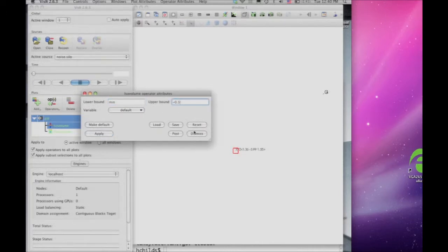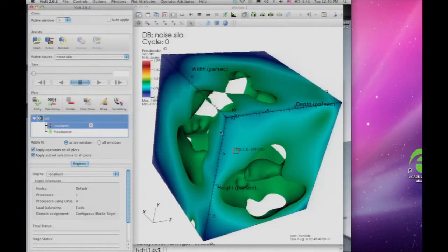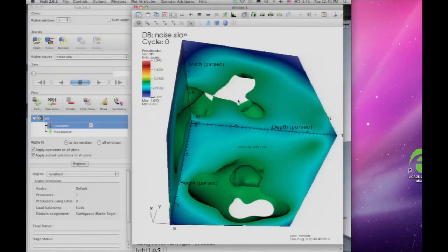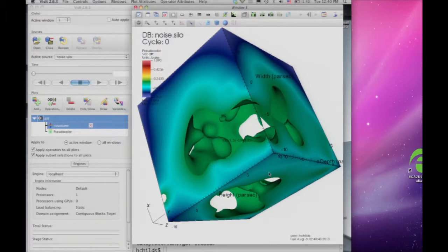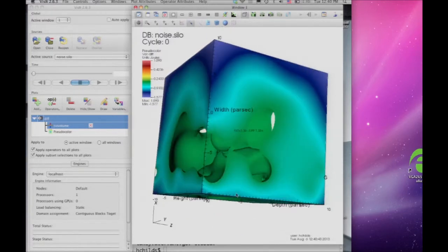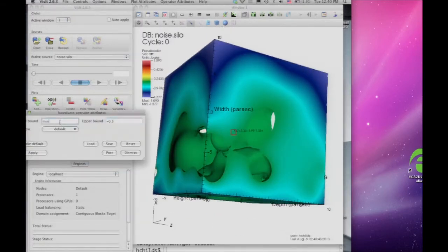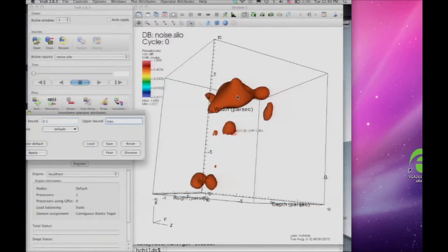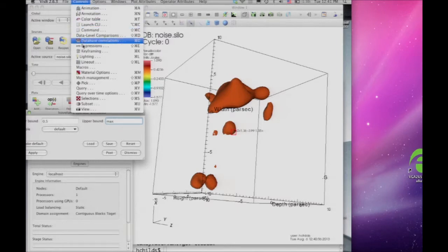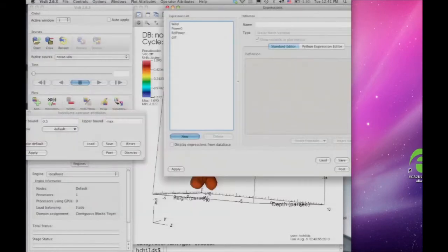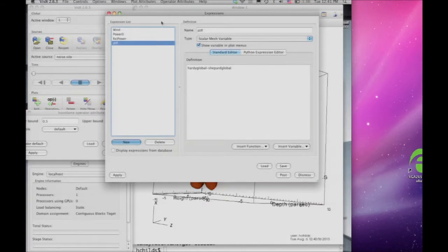Mesh quality, so if you have an unstructured mesh, ways to calculate shape, shear, skew, stretch, taper, warpage. There are various definitions to measure mesh quality, and you can make new fields that measure those. I will get into comparisons, but we actually have some neat functionality for being able to take fields from one file and put it onto a mesh in another file, which is a very hard thing to do in a distributed memory parallel setting, and then you can do differencing. Miscellaneous is where the really good things are, so gradients, curl, Laplacian. There's actually a lot of neat things in there.